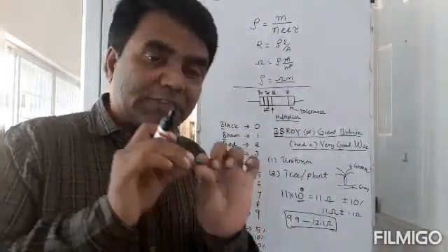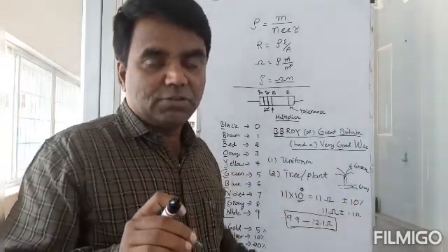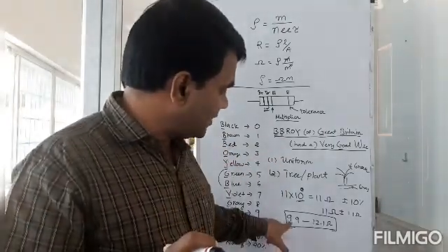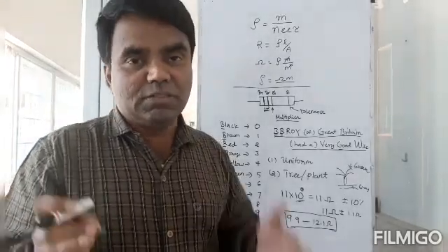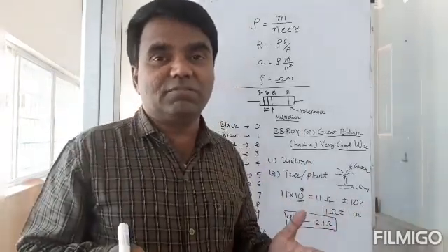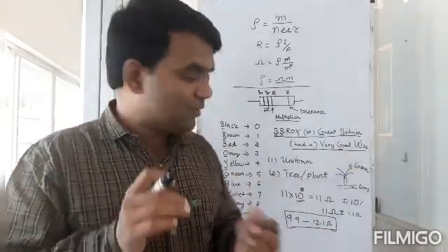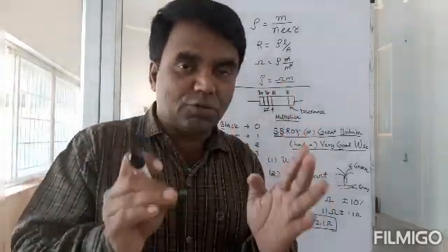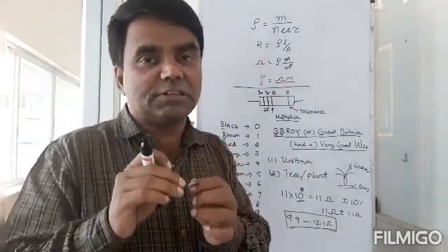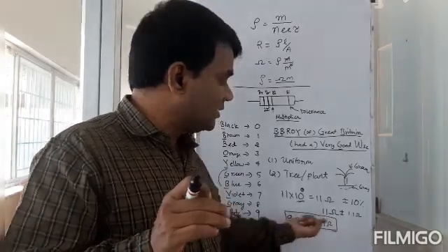So they say our stated resistance is 11 ohms, but it is made with 10% tolerance, which means that even though we say it is 11 ohms, the resistance could be anywhere between 9.9 and 12.1 ohms. It's within that range. It can still be perfectly 11 or 11.1, or even 10 or 10.5 ohms. But what is guaranteed to you is this: we say it is 11 ohms with 10% tolerance, meaning the resistance will be anything between these two values.